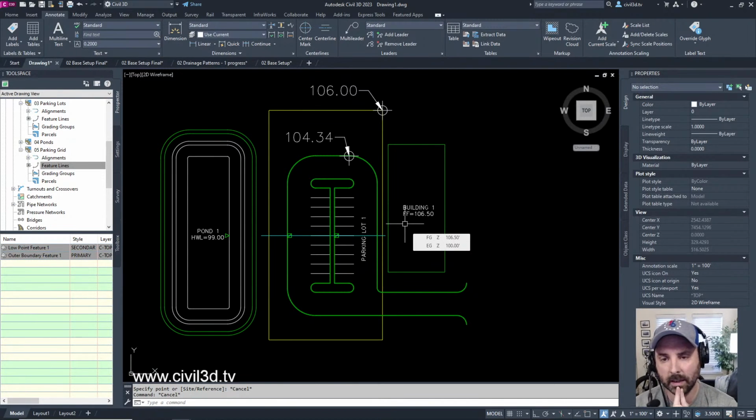The other thing is that sometimes when you're working in an office, a lot of people don't know how to make modifications to curb and gutter assemblies that are attached to the feature line, essentially what you're talking about. Some people don't know how to do that within your team. Most people know how to manipulate feature lines. So hopefully it's a way of simplifying by using feature lines and staying away from how unstable corridors and assemblies can be within the program.